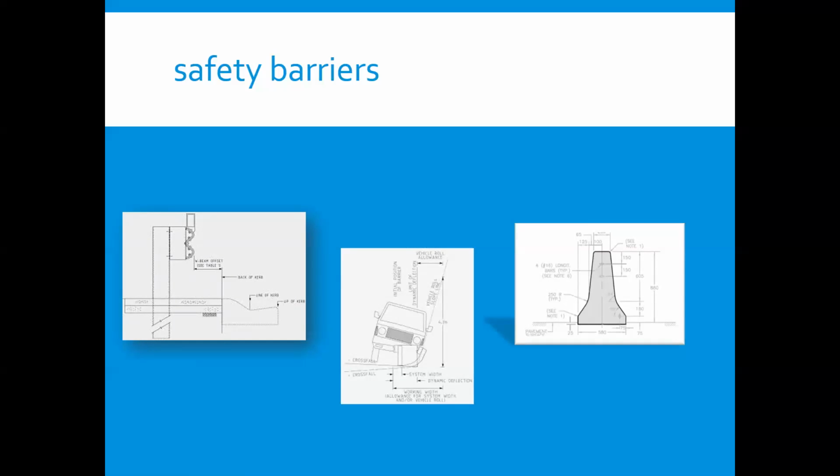Most road traffic authorities have detailed guidelines on installation of guardrails and end terminals. Care should be taken in meeting these requirements. The impact behavior of the guardrail and terminals should also be considered to ensure that the selected system is appropriate for the intended location.